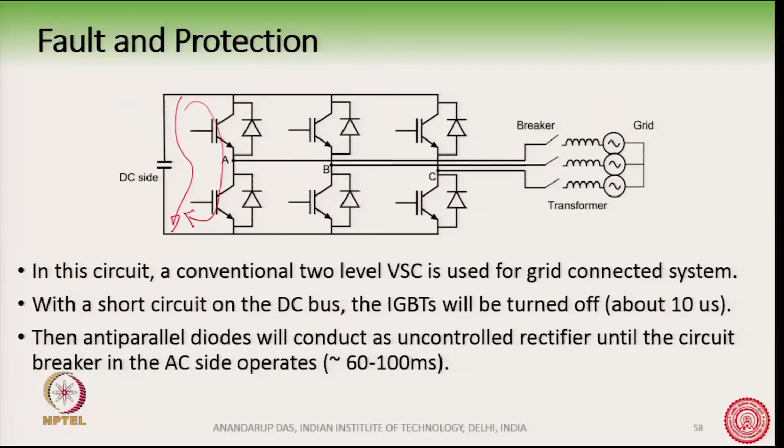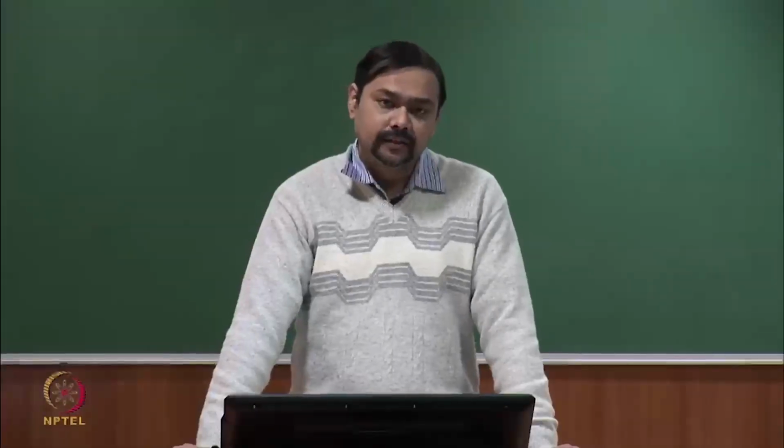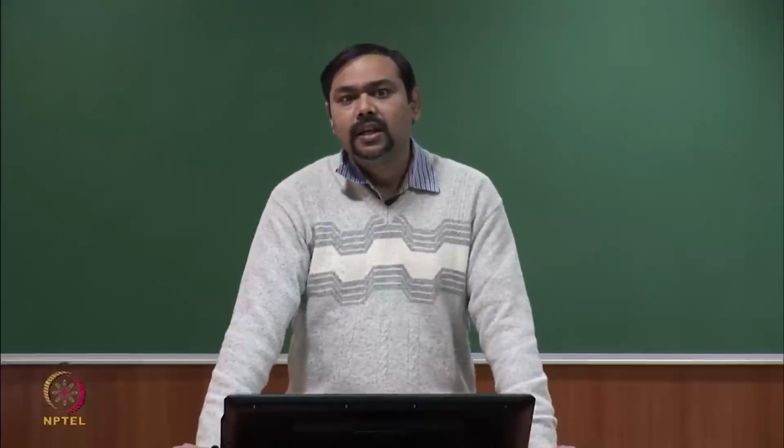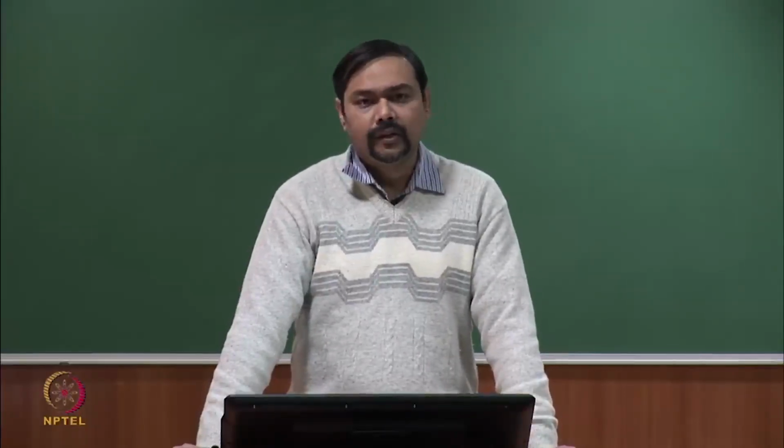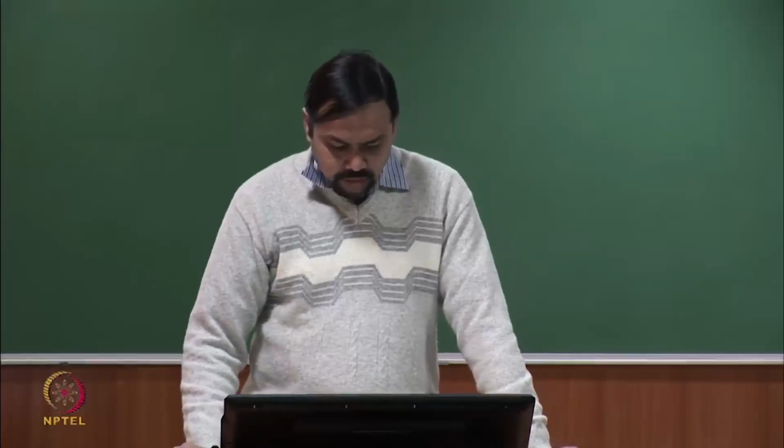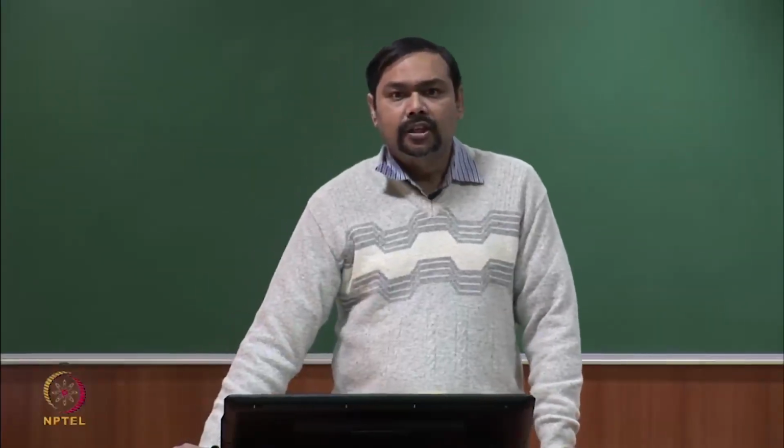Here it is a dead short circuit, and the whole energy of the DC bus in the capacitor will now be dissipated through these two transistors. It will flow and the current will rise very fast, and this is a potentially destructive situation. So, there will be local hotspots inside the transistor, and then eventually it will burn out. The bond wires will lift off, or it will completely burn out. So, we generally shut off the transistors during this time.